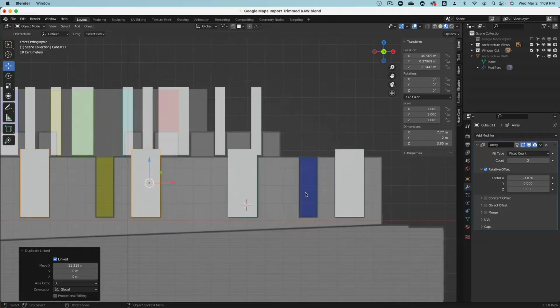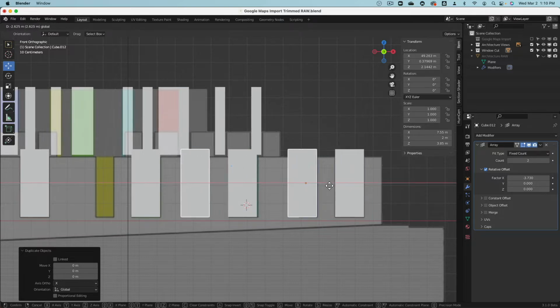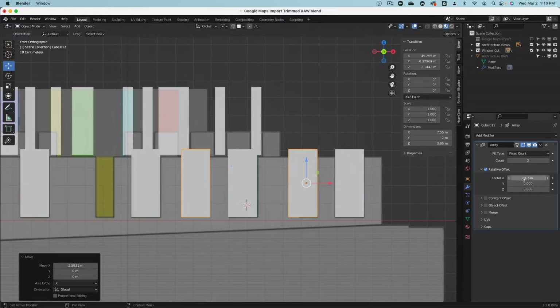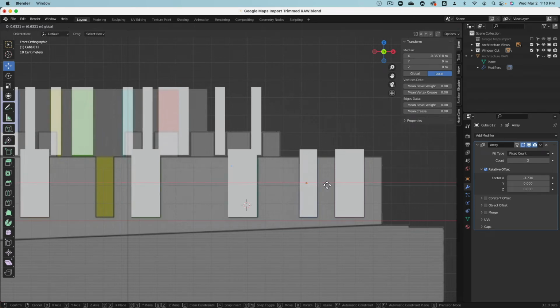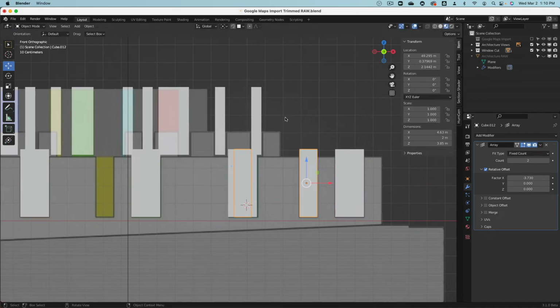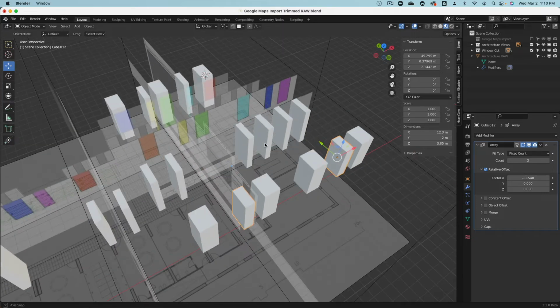Beautiful. How do we do this? I can say select this one, Shift D and escape. Bring this over to here. Then edit mode. This face is still selected, so I bring this in, release, exit edit mode via the Tab key, and then move this one over to there.